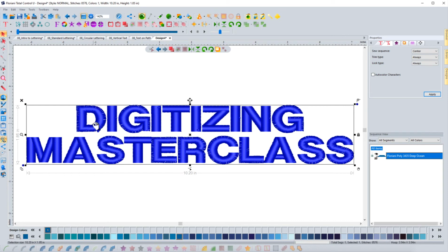And after it finishes a letter, it'll trim and it'll go in and do the next letter. And so there will be no jumps. I don't typically do that. I usually use never or auto. Auto is pretty neat because what it does is it looks at the distance between. And if the distance is greater than, let's say, 5 millimeters, it's going to automatically trim. And if it's less than that, it's not going to trim.